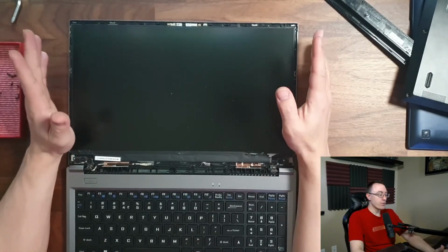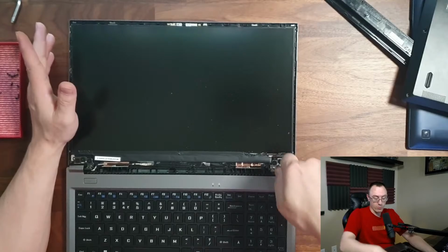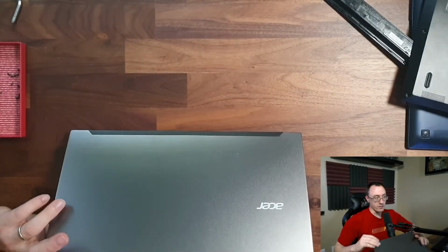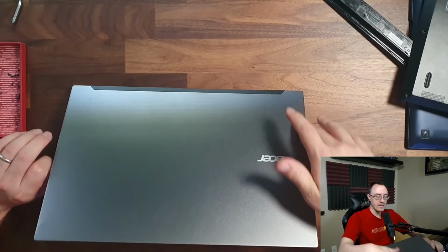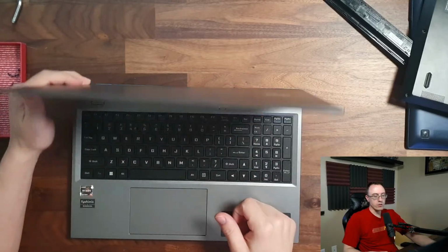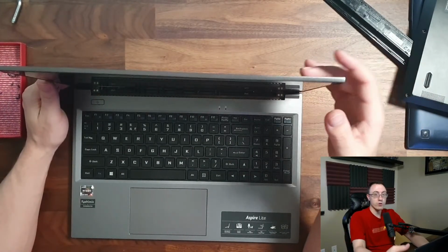Now, you can remove the screen in a one-way disassembly where you will damage it by breaking it and prying up underneath it. And I wouldn't recommend using a heat gun to heat up the adhesive on the back here because you have to use so much heat to get through this chassis that you will usually malform the actual screen itself and burn the screen itself before you start to loosen the adhesive.